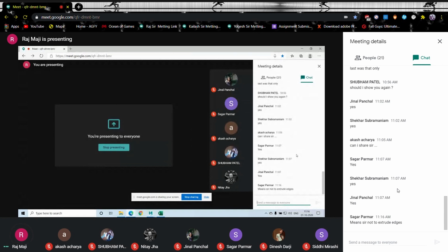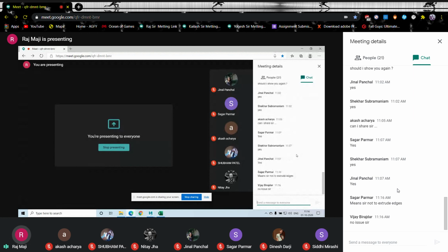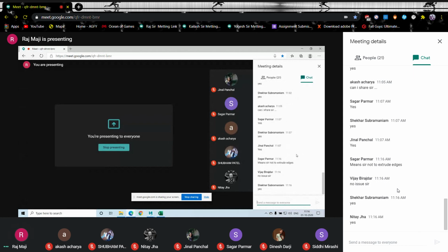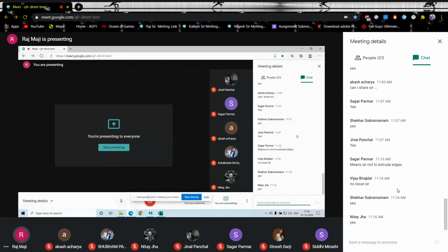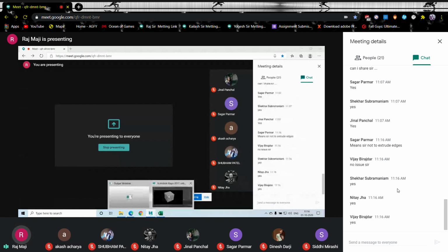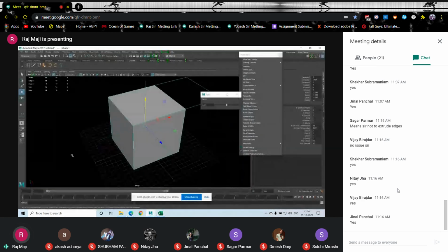No, no, guys, I'm not talking about that. What I'm asking is, you understood how the normal placement should be? Means the normal placement has to be on the outer side of the object. You always check after making a model, you come to the normals, and after some time your experience will tell you if the normals are correct or not. You will automatically come to know by looking at it. So the normals should always be outside.